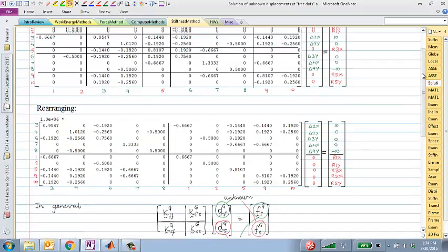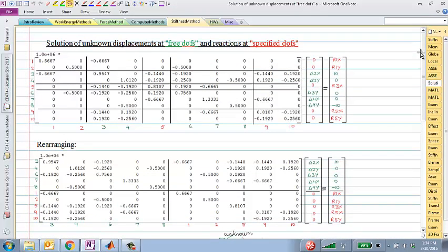of equations. So just to remind you, the overall idea for this method was that given a truss structure, we'll divide it up into elements, find the force displacement relationship for each element in its local coordinate system first, then transform it into its global coordinate system, and then simply add it or assemble it into this big system of equations.